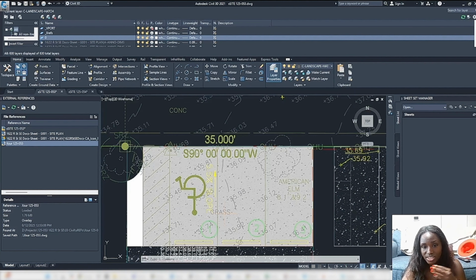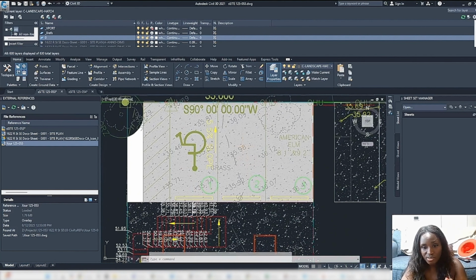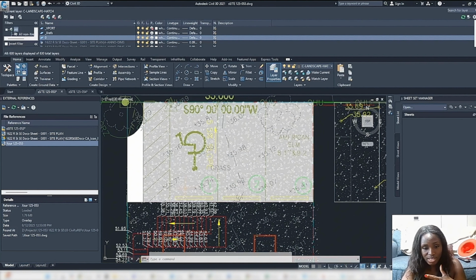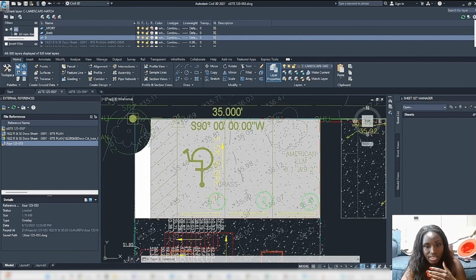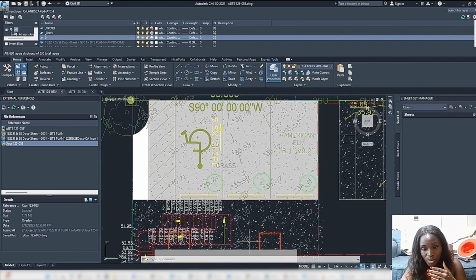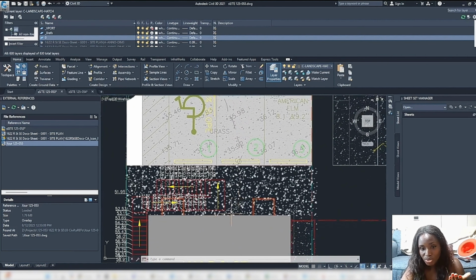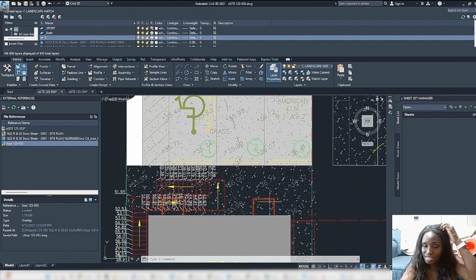So this is a grassy area. It's naturally going to be lower. And we're adding impervious pavement because we're adding this pavement. This needs to be raised so that water is draining away from the building, because if water is going towards the building, that means water is getting trapped here and you're going to have muggy basements.